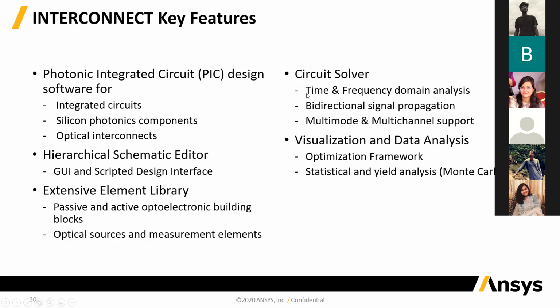It can perform time and frequency domain analysis. The optical signals that flow in your circuit are bidirectional, so you can see effects coming from reflections at the interface between different components. And the simulations are multi-mode and multi-channel. Finally, once you have your simulation done, there are visualization and data analysis tools that allow you to look at results. When you're doing circuit simulation, you also want to do a statistical or yield analysis, and that can be done by using the Monte Carlo tool.